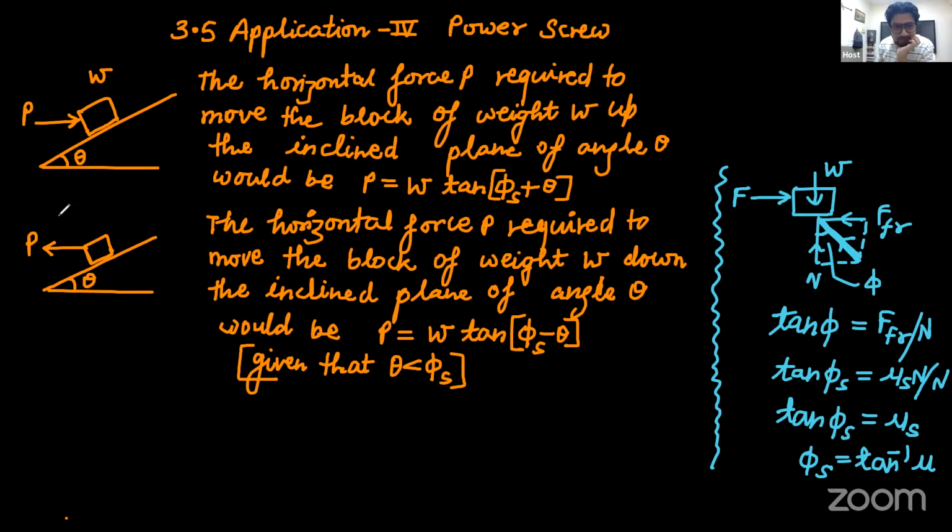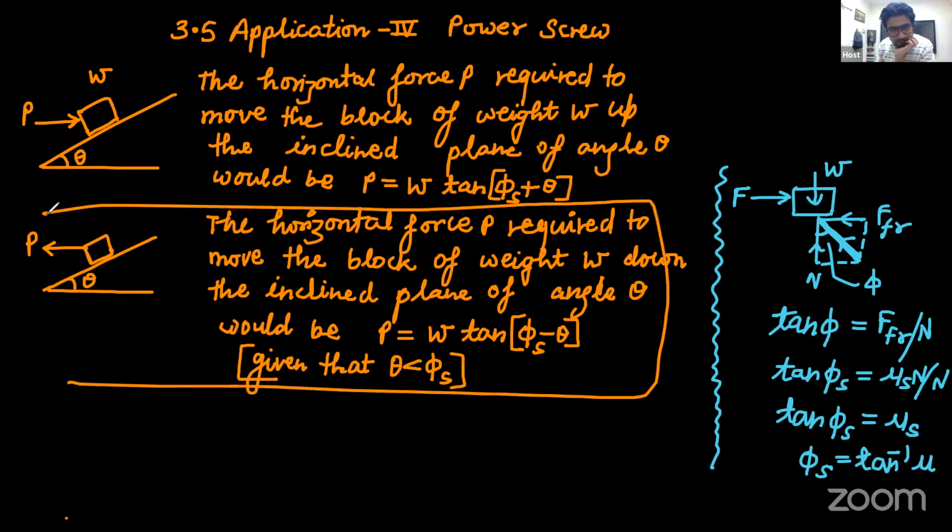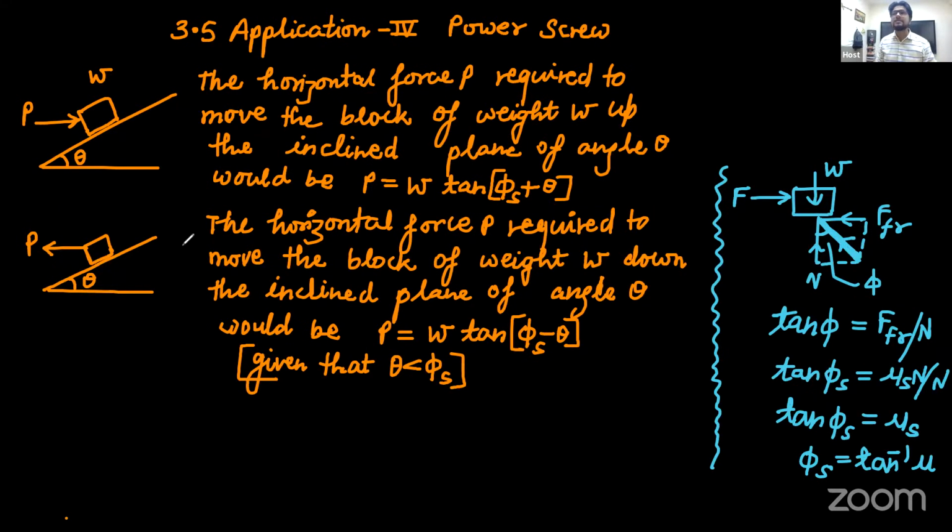Its own weight is enough to keep moving it down the plane. So you need to apply force to lower the weight down the plane only if the weight is not automatically coming. If theta becomes more than phi s, the weight will automatically start coming down the plane. So I request you to please remember both these cases.